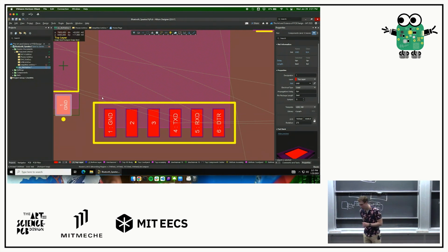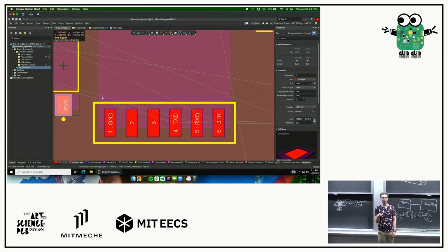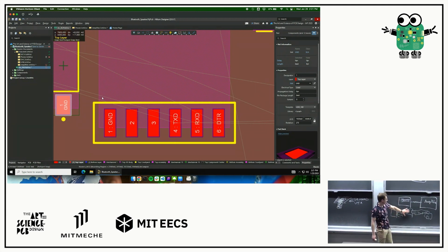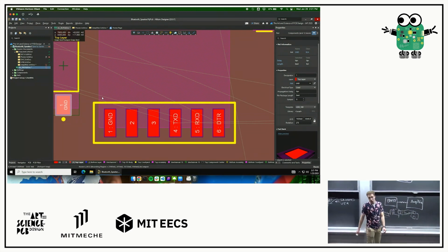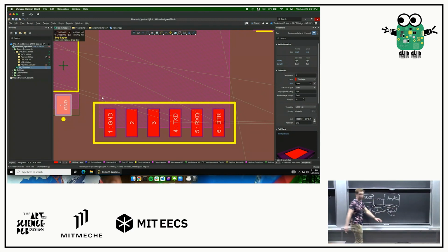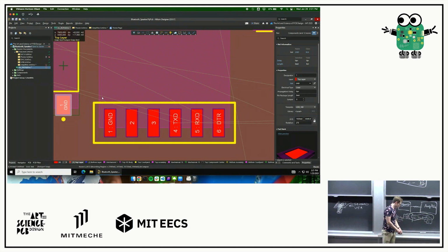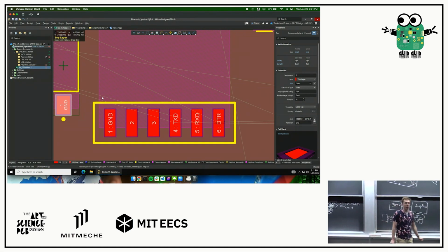There's also the lovely upper bound on making things large, where it's as large as you can physically make it while not being too ridiculous. Like if I have the output of the boost converter and the input of the amplifier, I could also just take a 100 mil trace and go around this entire thing. That's also valid, and I've done that before. It looks a little stupid, but if you don't want to bother with current calculations, maybe that suits your fancy, or maybe you're too ashamed to even consider something like that.